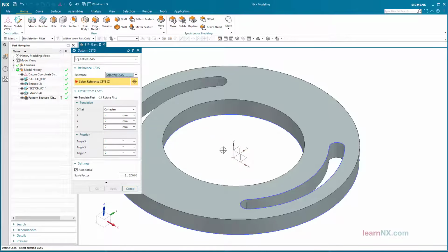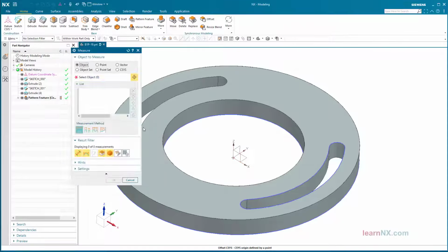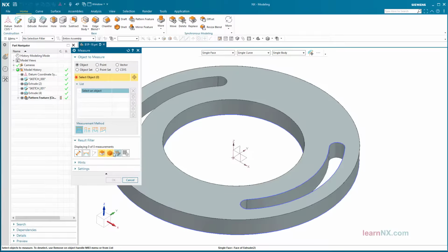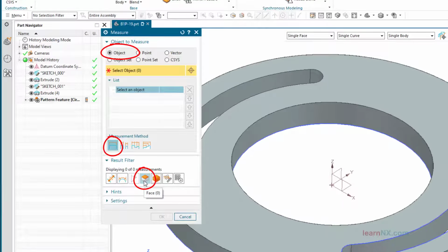Select the existing CSYS. Under Y and Z you could simply enter values, but the CSYS would then stand rigidly at that position. However, in order to align the CSYS associatively with the modeling, not values but formulas, measurements or references should be inserted. Pass measurement. Therefore, the radius of the mantle surface is measured next and entered as a measured value, for the offset in the y-axis. Click on the small arrow and select Measure. Select the surface area with the settings shown.